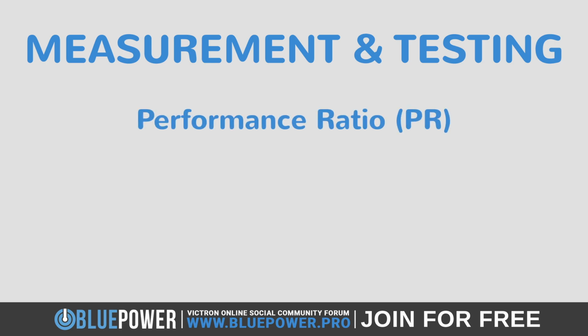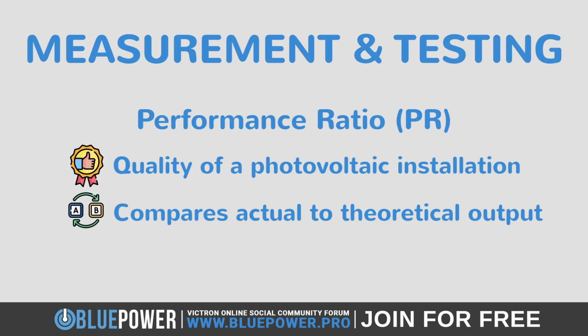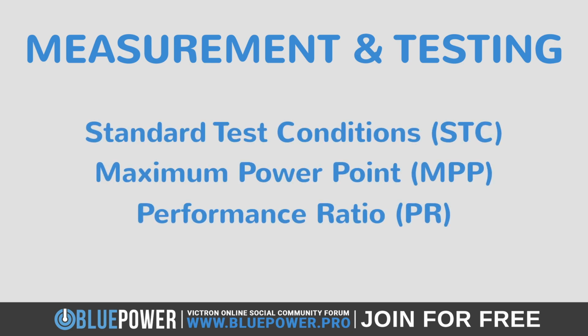The performance ratio, or PR, is a measure of the quality of a photovoltaic installation. This performance ratio compares the actual output to the theoretical output under ideal conditions. PR accounts for various losses in the system, such as temperature effects, shading, and inefficiencies in the electrical components, providing a realistic indication of system performance. By employing these standardized conditions and metrics, the efficiency of solar cells and systems can be accurately measured and tested, facilitating improvements and optimizations in solar technology.